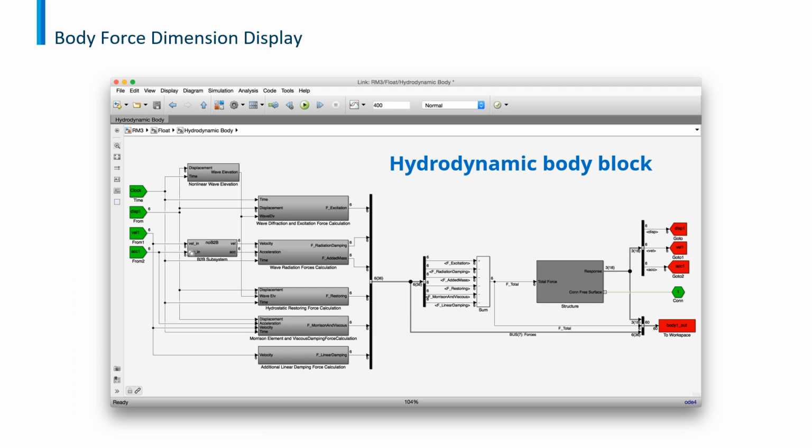Notice in the right half of the diagram, the lines are thicker between some of the blocks. The thicker lines signify that a bus was defined. In Simulink, buses are used for more efficient routing of signals, so that related signals are clubbed together and they could be used in different parts of the Simulink model more easily.